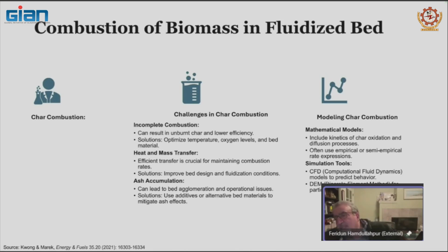These are all possible designs, but very good question. It's up to you and depends on the fuel type. Sometimes when the moisture level is really high, you want to dry it externally. You may even use mechanical separators like centrifuges to push the moisture out, and then remove the rest thermally.